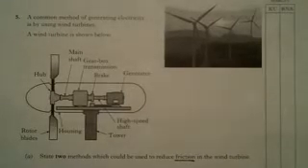Well, first of all, the turbine shaft will be mounted on bearings, so you could have better quality bearings, probably roller bearings, something like that. And we've got a lot of cogs moving around inside the gearbox, so we want to reduce the friction there, so probably use a better quality lubrication, oil or some such like.